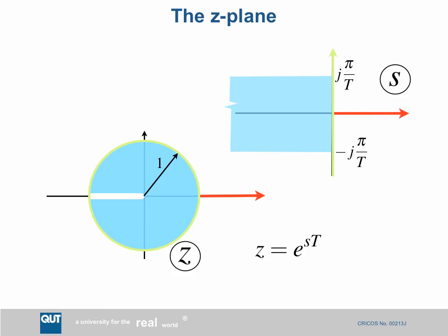This area, the positive real axis, where there are unstable poles clearly, is mapped to the positive real axis on the z-plane, but it starts at 1 rather than starting at 0 as it does on the s-plane. It's offset by 1. The negative real axis, which is infinitely long because it goes from negative infinity to 0, maps to the interval 0 to 1. And the bounds of the band in the s-plane, two infinitely long lines, are mapped to one finite line segment on the z-plane.